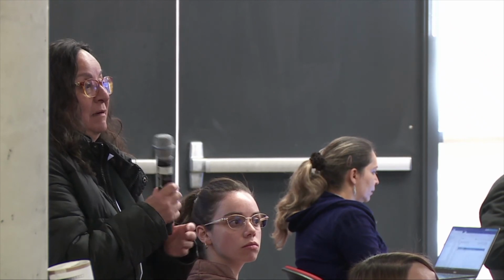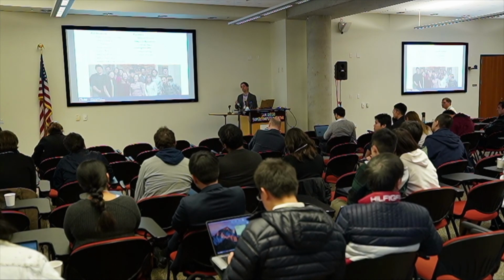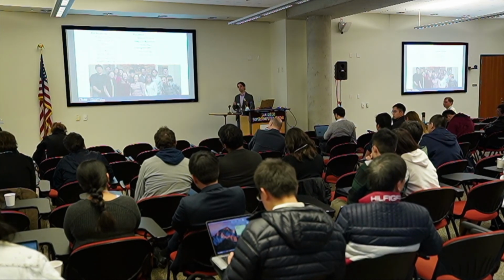Yeah, so we have looked at this. Silicon dioxide does degrade, so that's what's really limiting the lifespan of these devices. The silicon dioxide does get dissolved away over time, and it forms a biocompatible byproduct after the reaction. We're hoping to slow that dissolution rate further by adding capping layers that limit the degradation. The silicon is also biocompatible. It does dissolve as well over time, and it does get resorbed. We think it will all be biocompatible long term.